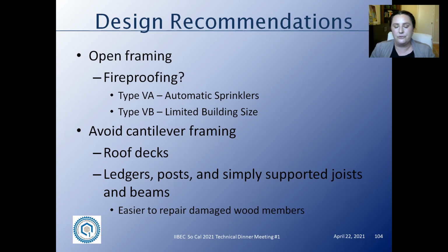One other way to avoid having to do these inspections altogether is to no longer do any kind of exterior elevated elements and just make everything a roof deck over occupied space. There is a problem with that, because now you've increased the risk on those systems. By having a roof over occupied space, you now have a much higher risk of waterproofing damage to the interior because you are now over occupied space.